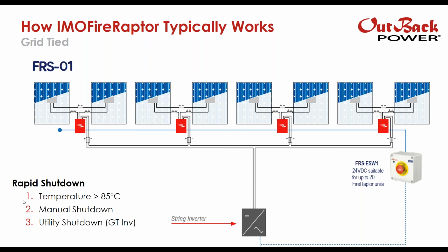So this shows, like I said, 2 panels. Anyway, this configuration is similar to what Tigo does too. Essentially, if you were to cut the power supply to the module level power electronics, this initiates a rapid shutdown. Whether the meter is being pulled, or you press the button, it's a rapid shutdown. But this is a string inverter.